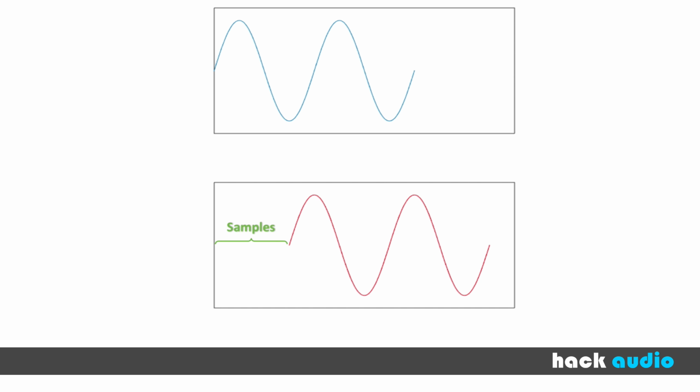Now, when we're working with a shorter time delay, it's also helpful for us to think about other units. In this case, this is a relative unit compared to the length of the period or the length of a cycle. So for this signal, if we compare the blue signal to the red signal, this is actually 3/4 of a cycle that we've shifted the signal over. So it's relative to the length of a cycle. Or in terms of other units, this would be a 270-degree shift. Or we'll look at later on how we could also look at it in terms of radians. 3 more different units that we can use to describe this time delay.